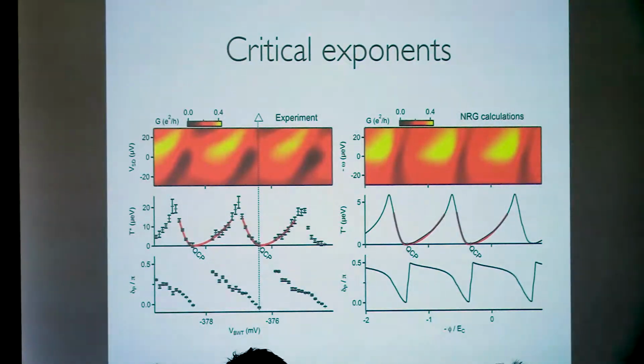We can take both of these expressions, and in particular using the exact crossover expression on the previous slide, try and extract what this T star is as a function of the gate voltage on the large dot. And somewhat unsurprisingly, as I add one electron, it's not so different from adding 2 electrons to the large dot. There are already hundreds of electrons on it, so it shouldn't really matter intuitively.